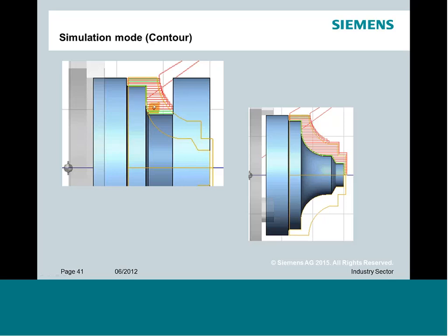So here you'll see the cut amounts will now vary based on that shape that I drew for the stock, as opposed to always being kind of stuck in saying, well, it's got a half-inch of material where maybe it doesn't on the front, and maybe it doesn't up top. So you can get a much more optimized cutter path if you take the time and draw the stock.